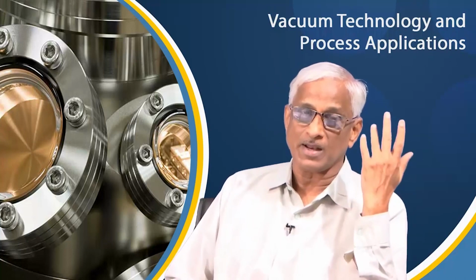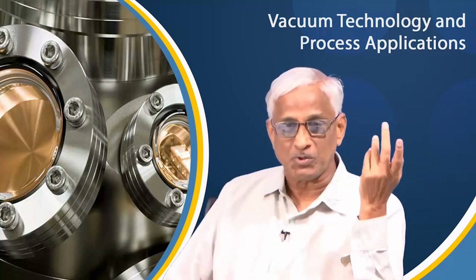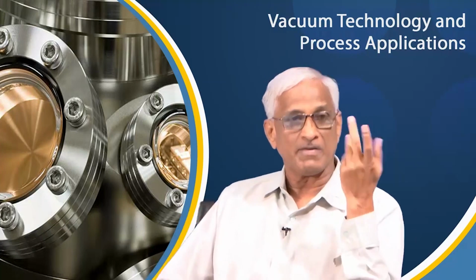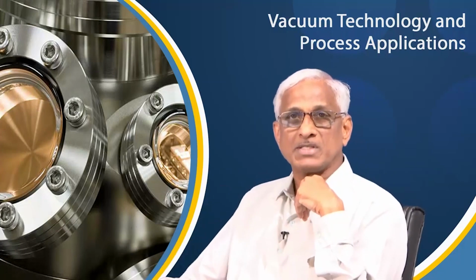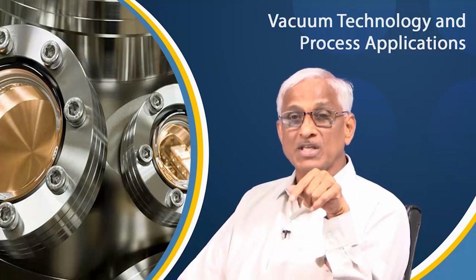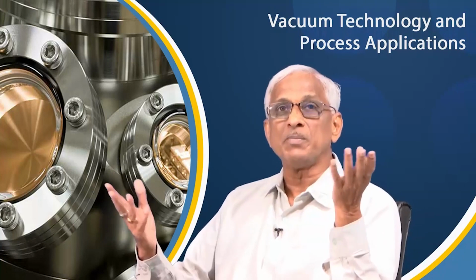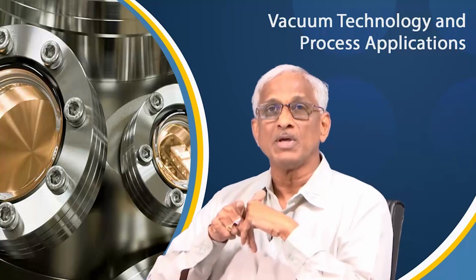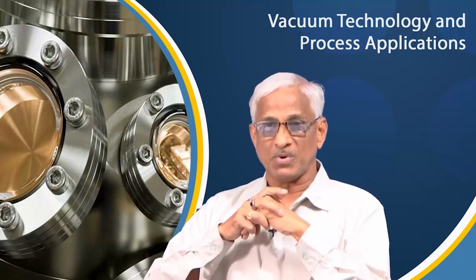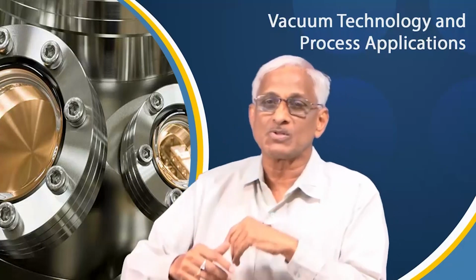But earlier rotary pumps and piston pumps were doing the same duty. In fact, they are even having longer, higher pumping capacities. But what we require is quality, it should be dry. So, things are changing depending on the application. Why I am discussing pumps here is, depending on the application, it is not only the quantity of vacuum that is important, the quality of vacuum is also equally important.